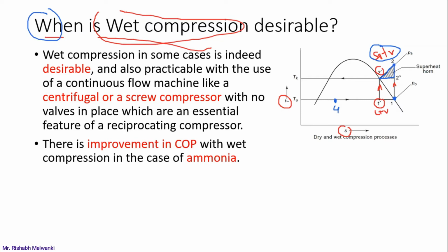Central AC has a number of parts. The part which is responsible for the cooling effect of the water. What happens in central AC? We have three refrigerants basically. The main refrigerant, whatever is being used, first chills water. Then that water is sent to different locations inside the building, and that in turn chills the air with the help of the air handling unit. So in very big tonnage central AC, a centrifugal type of compressor is used, and in medium or small systems, a screw type compressor is used.